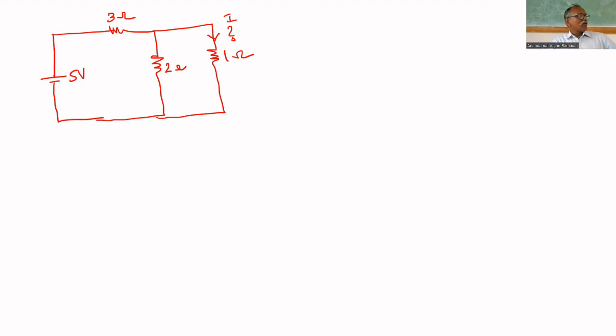While finding equivalent resistance, where do we have to start? If you start at the correct point, then only you can proceed. Always start from the tail. This is a single source circuit, that's why we can simplify and solve. Suppose there are two sources, we cannot apply this. We have to apply some theorem, Kirchhoff's voltage law, or a nodal equation. You have to write it and find it.